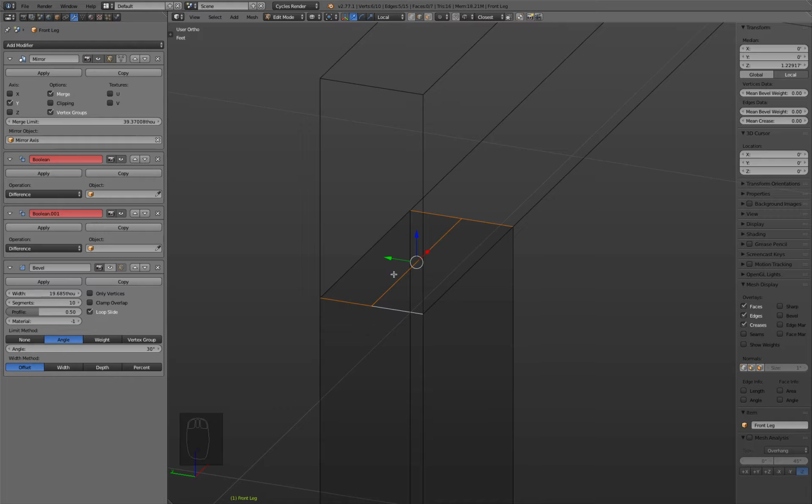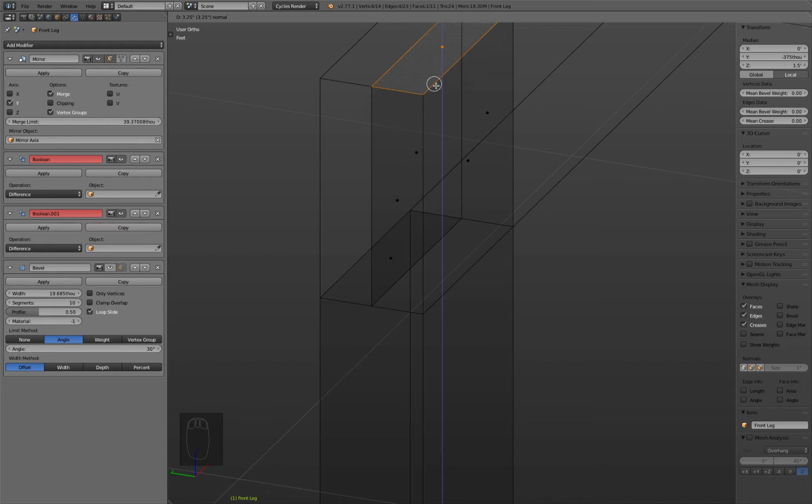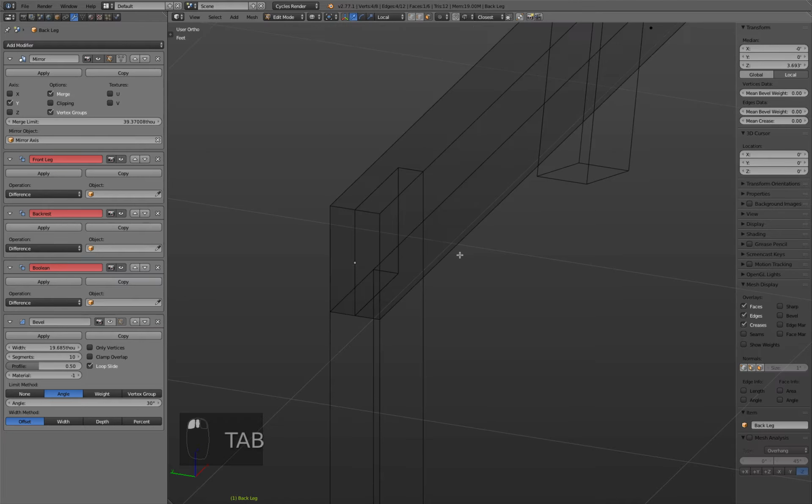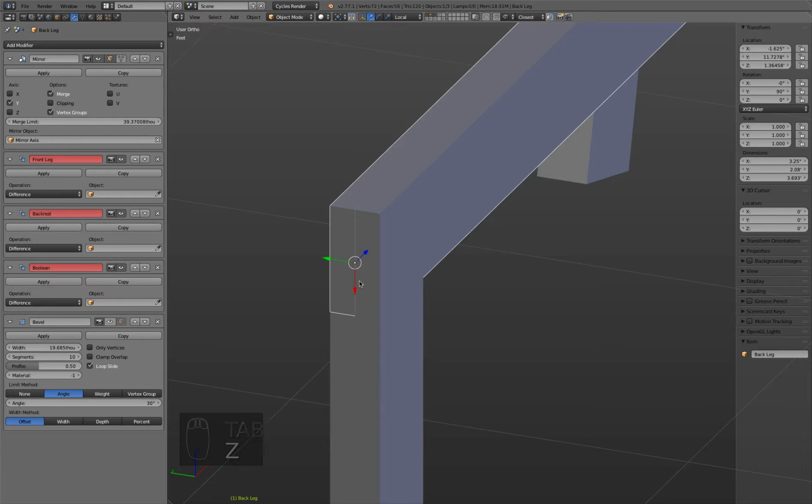And now you see we created this new edge. And this new edge is needed so that the initial face will be sliced into two faces. And now I can press E to extrude this one up, and then with control snap, for example, to the upper edge, or based on what you have selected, the vertex. There. Okay. Now let's do the same on the other side. So A, deselect everything, move this back, snap, K, hold control key, click, click, enter, select the face, E, control, snap, left mouse button, click, done. Perfect. So now we have the same